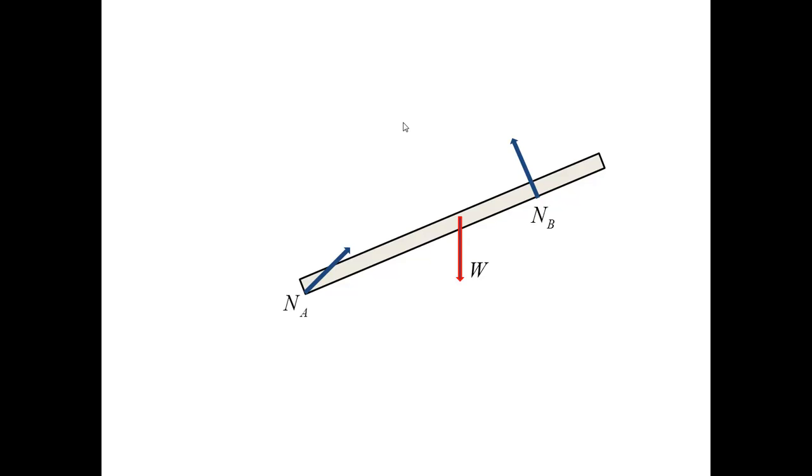You may look at these 2 points and recognize that both of them involve a contact of a smooth surface with a well-defined normal and a sharp corner where the normal is poorly defined. And in both cases, I choose the normal by looking at the smooth surface. This free body diagram looks very simple, but in order to quantify it, we need to identify the orientation of the forces involved, and we also probably need to know the lengths A, B.